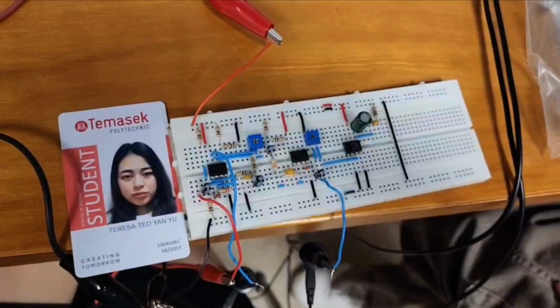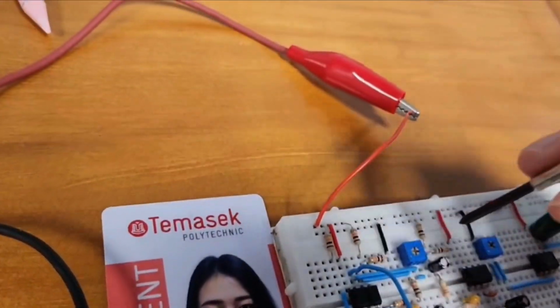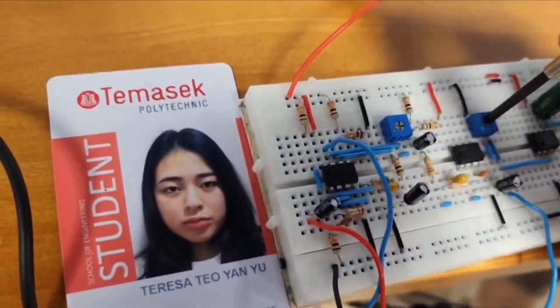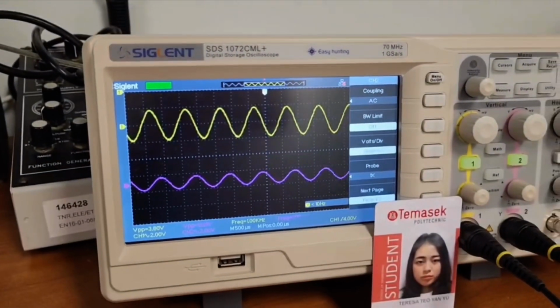At 1000 Hz, unity gain does not apply to the voltage input and output, and it will no longer be equal to each other. After 500 Hz, which will be explained later on, there is a drop in the voltage output. Thus, the final output will be the maximum sine wave attained without being saturated.